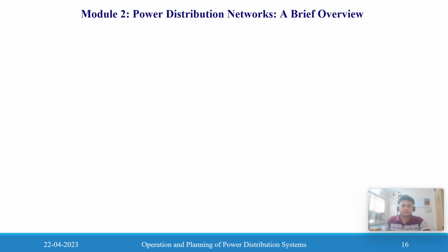The primary distribution system has a voltage level of 11 kV or 33 kV, and the secondary system is at the utilization voltage level. In the literature you may find that, according to IEEE, distributed generation capacity should not be greater than 10 MVA. But in some literature you may find a microgrid having more power capacity.